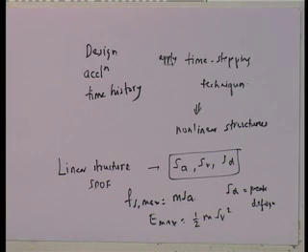If you have a single degree of freedom linear structure, the design spectra themselves give me all the design responses that I am interested in. The peak value of the force: what do I design the supporting structure for? Well, for M into SA. What is the peak deformation that I am likely to see, so that I can design certain systems to take that deformation?